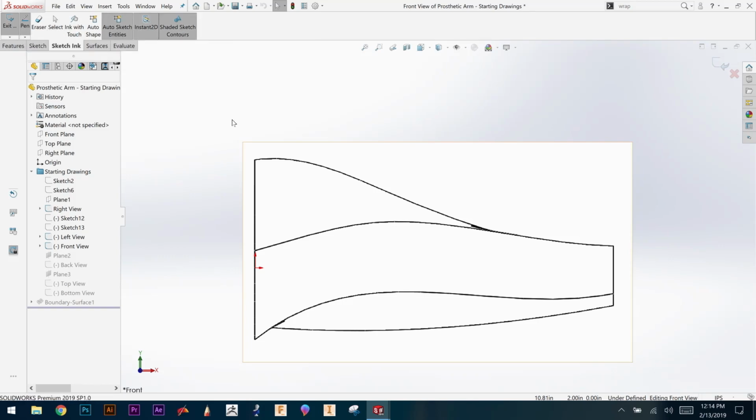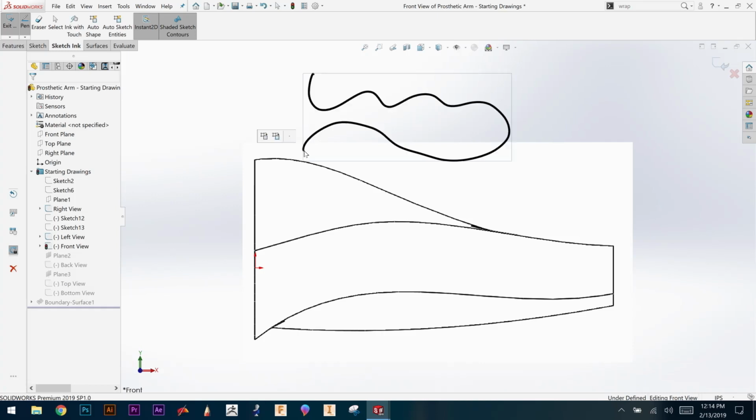When I started doing my workflow, I had this auto sketch entities turned on. So you can turn that off, and now I'm just drawing. So it's still capturing that path that I drew on screen, but it didn't convert it to sketch geometry. There's actually this little context toolbar that appears, and if I select this one, which is the same icon as auto sketch entities, that's where you can change it back and forth.